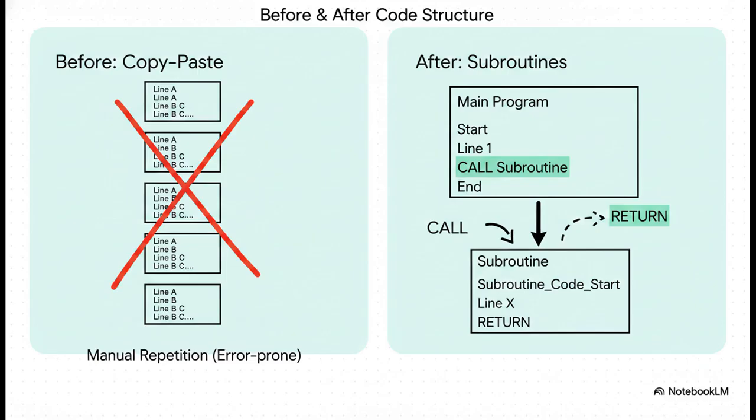Just look at the comparison here. The old way means manually injecting lines and lines of DECFSZ commands everywhere we want to pause. The new way, it shows the brilliant simplicity of working smarter. We literally just take that entire nested loop block, move it to the very end of our program as a standalone subroutine. Now, whenever we need a pause, we simply trigger it with the CALL delay command.